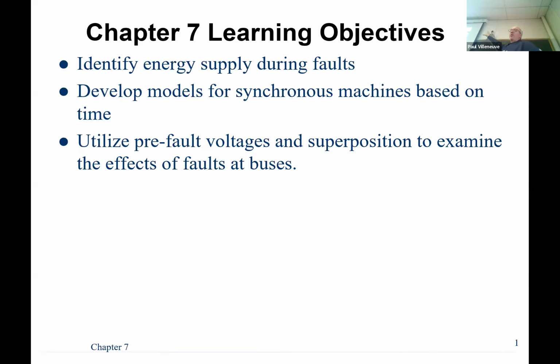Now, we're going to focus mainly on traditional energy systems, primarily because even though there's a lot of renewable energy, which typically would be called inverter-based, not the hydroelectric ones, but the photovoltaics and the wind, well, wind is kind of inverter-based, depending on the type of turbine you have. For the most part, though, we're talking about inverter-based, and there's really little to no fault current that those can provide when you compare them to the big synchronous machines.